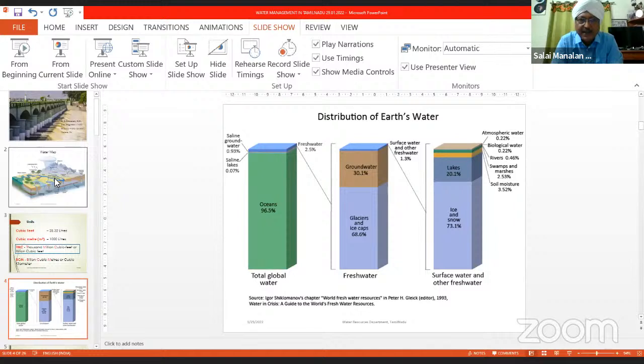Actually, at Meenjur, a 100 MLD plant is there. It draws seawater directly from the Bay of Bengal and desalinates it, and the produced water is mixed with the water available for catering to Chennai's requirement. Similarly at Nemeli, another 400 MLD plant is already working. For the drinking water requirement of the city where the population is more, the government of India or the government of Tamil Nadu has put up these seawater desalination plants. Even nowadays in power plants, we make use of seawater for service water and demineralized water requirements using desalination techniques.